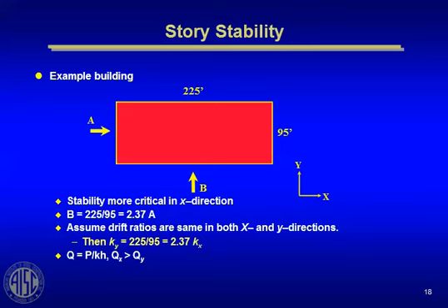So if you design this building for a certain drift index, you actually may have quite a bit of stiffness in the Y direction because you got a lot of wind area that you're designing for. But in the X direction, you don't have much wind area. It's much narrower face, yet you have the same weight, the same mass that you're carrying.